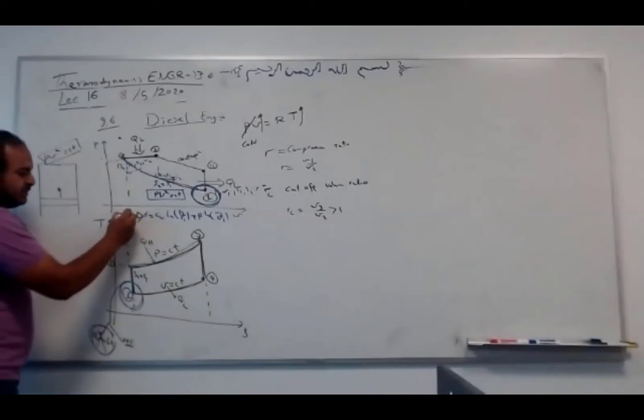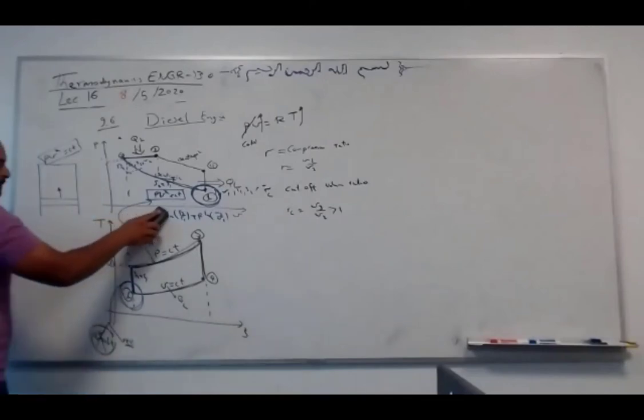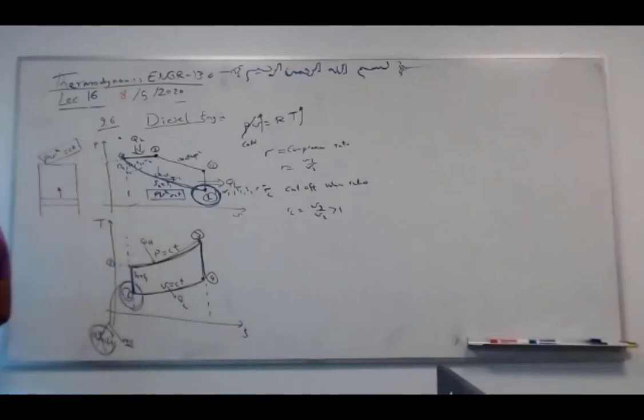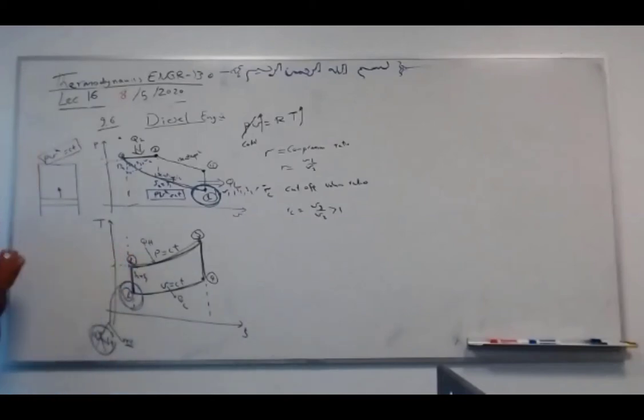If you put delta S equal to 0, you get this equation, for ideal gases. This isentropic relation is correct if there are two states with an isentropic process between them. Any question? These are the same curves. I can ask you to plot this or this.